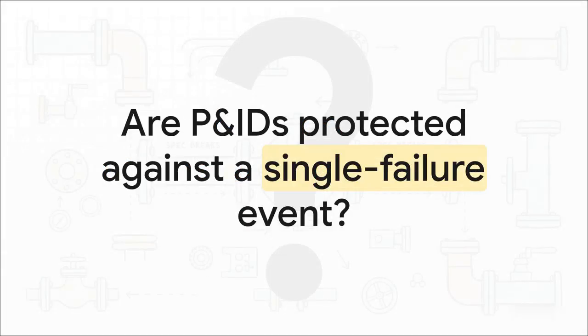So, I want to leave you with this final provocative thought. Go back to your desks today. Open up your current EPC project P&IDs. Trace the lines from the high-pressure sources and ask yourself, are your plant's piping systems truly protected against a single failure overpressure event at the spec break? Use this rigorous process safety methodology to evaluate your own facility designs.